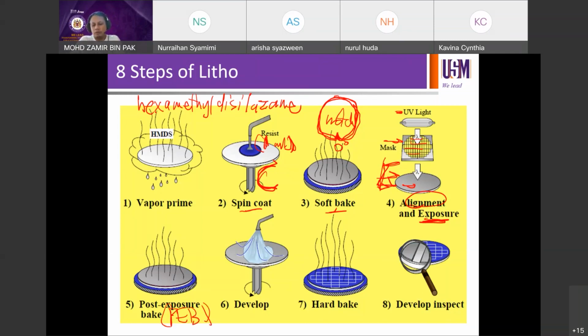At this point you have already printed the image in the resist, but you don't have features yet. If you look at the cross section from our earlier discussion, you probably already have something like this. Say you eventually want to keep the red shaded region as your features, but the unshaded region is still there. The image we printed is still in the resist and not removed yet. So it's called a latent image. It's already in there, but we haven't removed the soluble layer yet. We have printed the image because we have exposed it. So you want to make sure the image and the structure we end up with will be strong.